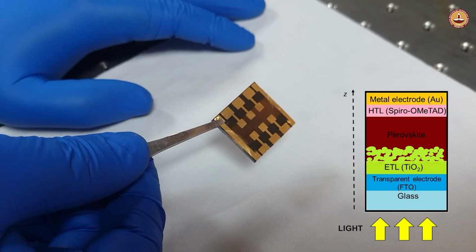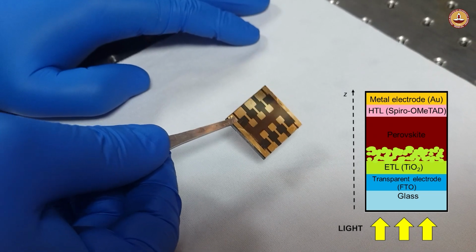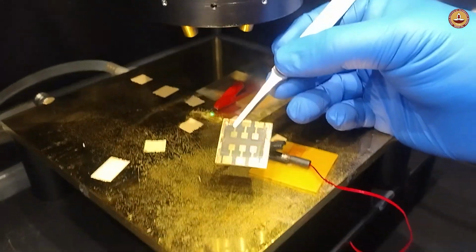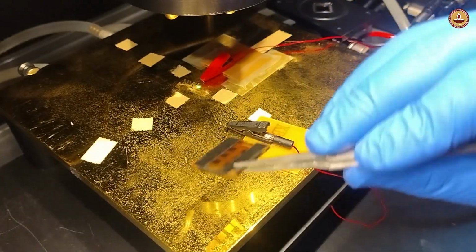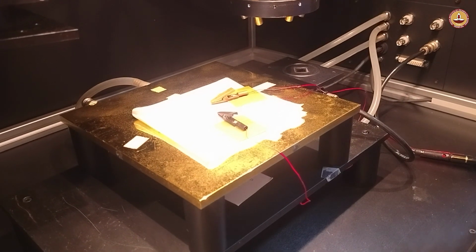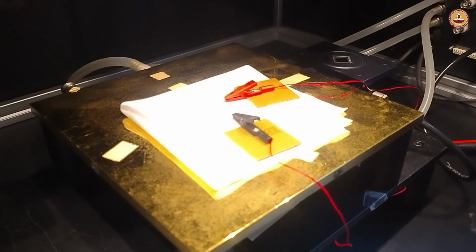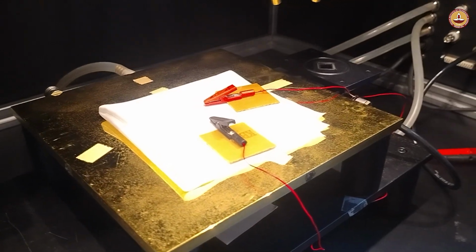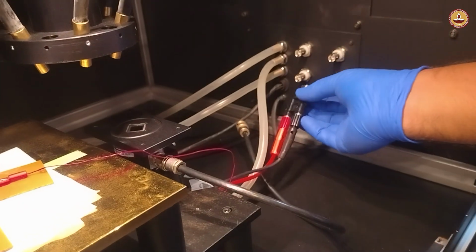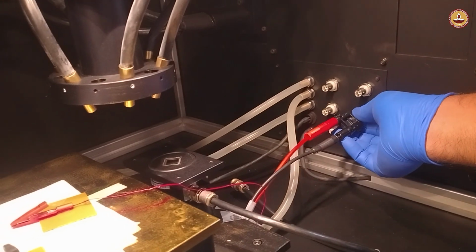Now, we will measure the EQE of the perovskite solar cell fabricated in our lab. The device is made in NIP configuration with 6 devices on each substrate. The top metal contacts of each device are extended to the left and right sides, and the bottom FTO layer is connected to the long gold pads located on the bottom and top edges. To characterize this type of solar cell, crocodile clips are used, as mentioned in the beginning of this demonstration. These clips are used to connect to the top and bottom contacts, and the connection is completed using a BNC connector to the detection unit.